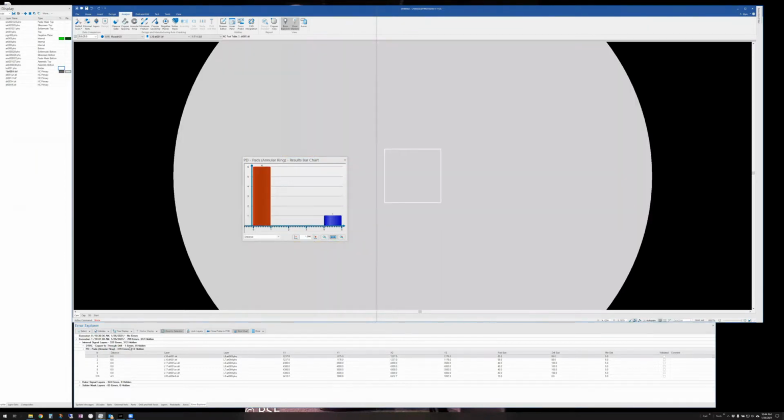So I've got a plated through hole that has an 85 pad with an 85 drill. And then I've got some 100 mil holes. These are non-plated with 40 mil pads. Another difference in the 160 is we would have split that up in the higher end, so they wouldn't have failed the regular annular ring. They would have been in there if you ran non-plated annular ring, but most people don't even run that, so they wouldn't have shown at all. It's basically just what we call a spot pad.